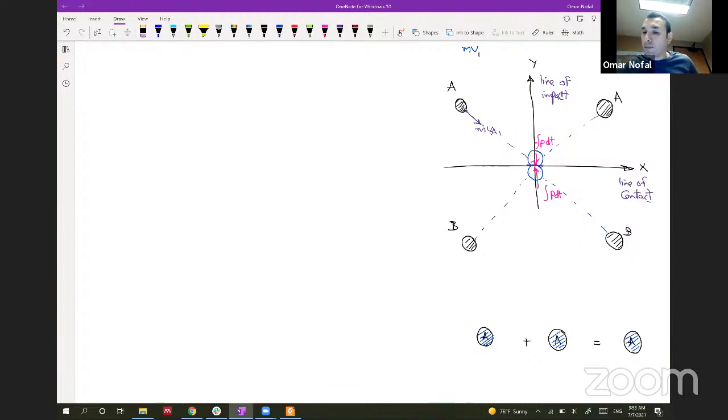After the impulse, it will go this way because we are in the same body right now, which is body A, mVA2. And body B goes this way with mVB1, and once it collides with body A, it will have a reaction this way, mVB2. So these are the vectors and these are the directions, and right now we need to solve this in x